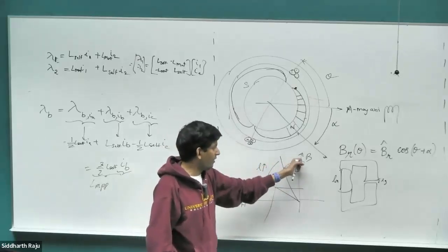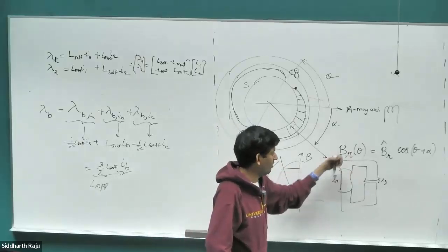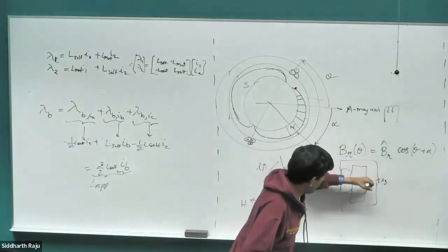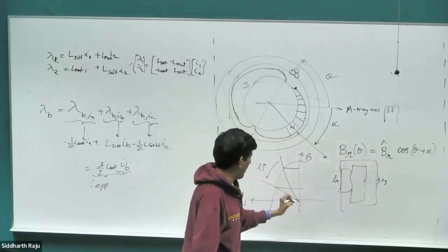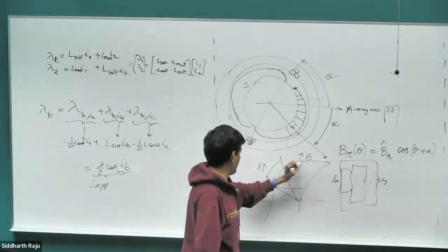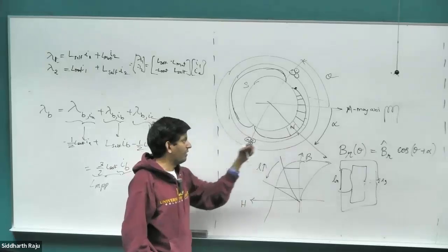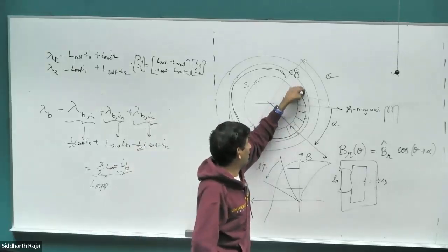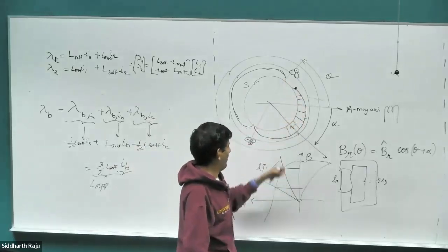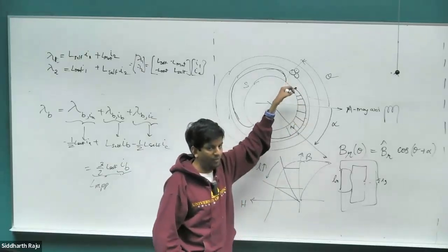It can have the same retentivity because you take this magnet, put it in an iron core like this, put a bunch of coils, and you pass a whole bunch of current. You basically magnetize this material. That's what this BH curve was. And once you take out the current, it would settle down to this retentivity value, right? If there is no air gap. But then you can have it such that the length of the air gap is very large here or very small here, so that we have higher magnetic field strength here and sinusoidally reducing magnetic field strength there, right?